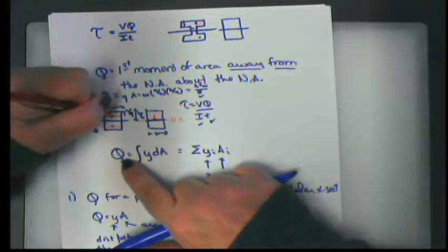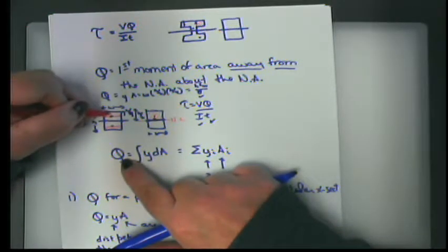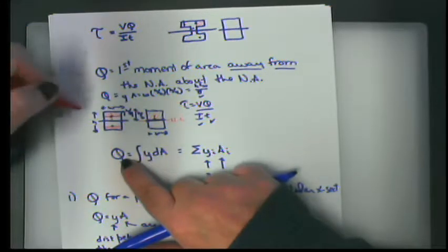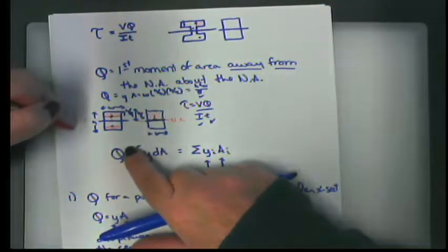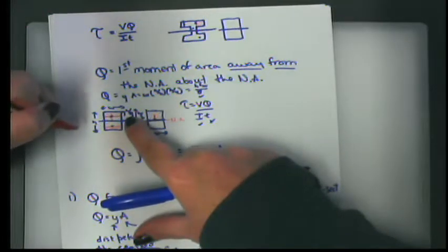My centroid then is going to be h over 8 from the top. But what is it from here? It's h over 4 plus h over 8, or 3h over 8, is my y. It's always the hardest part. And my area of this chunk is h over 4 times w.